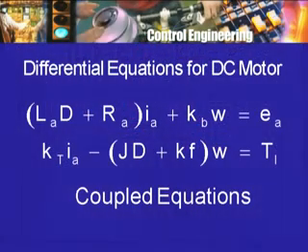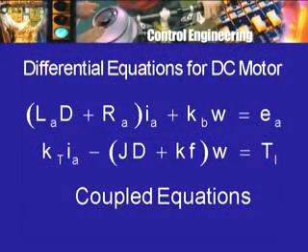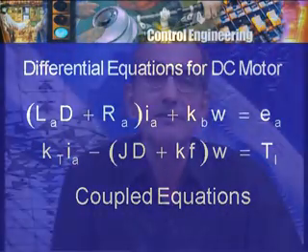Now, what we did earlier was to apply the Laplace transformation to these equations, whereby the D was replaced by S on the left hand side. Of course, because of the derivative property of the Laplace transformation involving initial values, we did obtain initial values of omega and IA. Those terms we transferred to the right hand side and said that we will not look at them, or will assume that the initial values are 0 equivalently. Now, in the time domain approach, of course, I am not going to take the Laplace transform of these equations and then do any further manipulations.